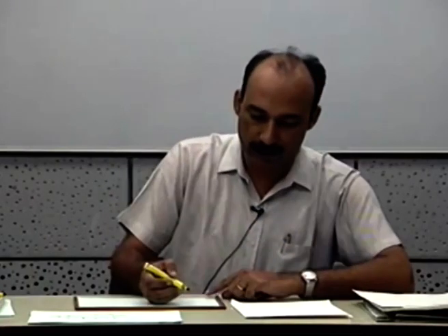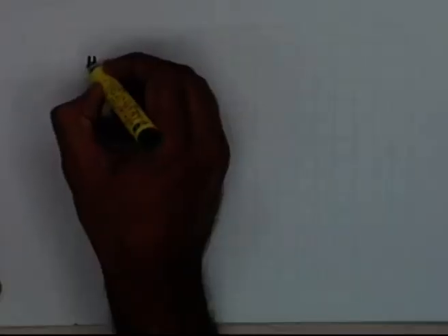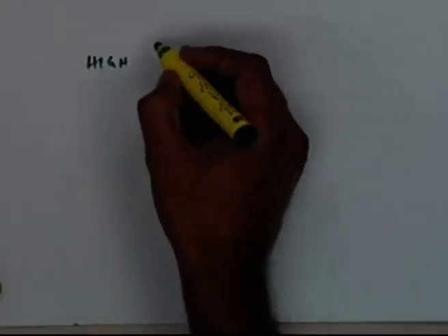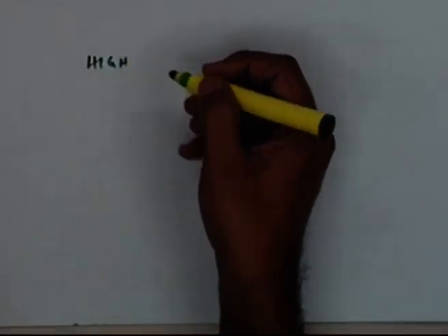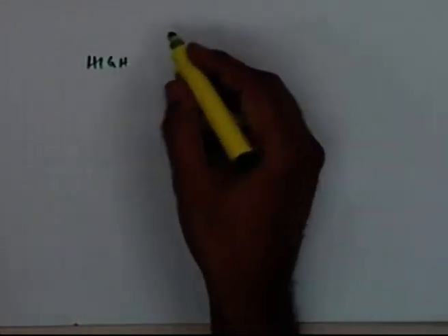And there are two cases which have been considered. We have already seen that the gradient of the border will make a lot of difference in terms of what is the normal depth which is getting established, and we had said that if the slope is more than 0.4%, then we'll call it a high gradient border, otherwise we'll call it a low gradient border.